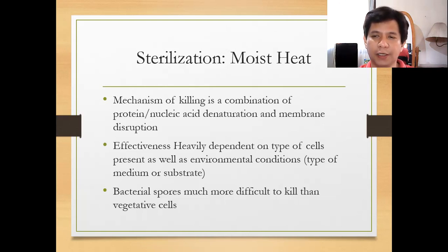Basically, there are bacteria that are relatively not affected by steam, especially those spore-forming bacteria. They can survive steam for a reasonable length of time under exposure to steam. So all you need to do with this type of problem is just to increase the length of time that you're going to expose the system to steam.